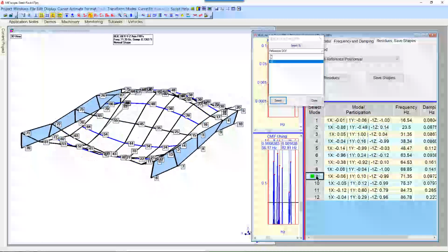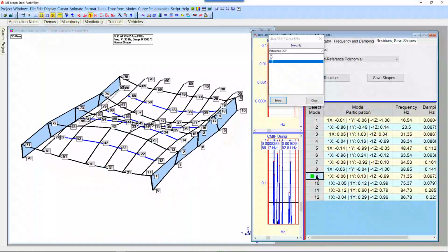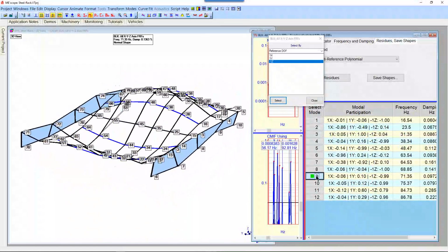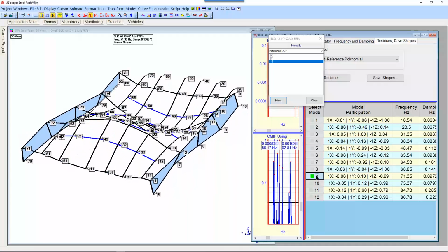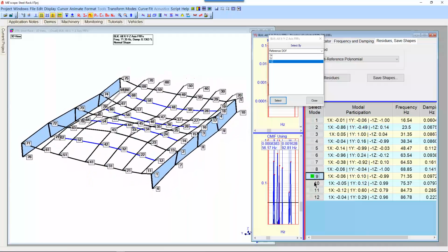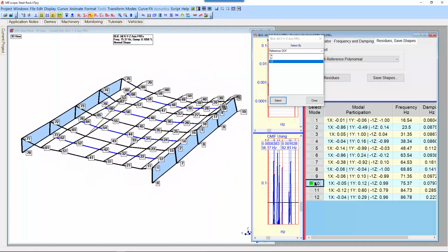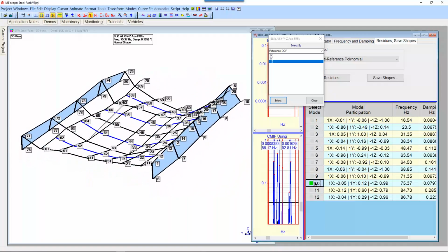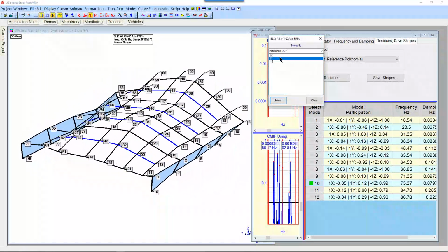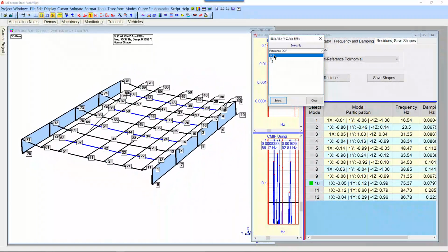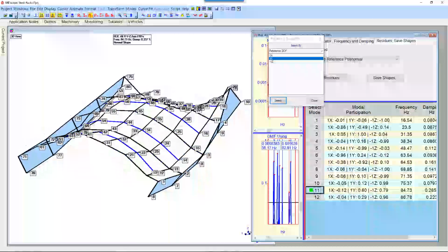Number 9, this again is a Z mode. Boy, we don't have a name for that. We certainly have its frequency. And so we can always identify the modes by their frequency. But this is, maybe you call it an oil canning of this grate, kind of an oil can mode. Here's a, what is this mode? This is another Z mode. A little bit strange as we get up into the higher frequencies. Maybe we call that second bending. The curve fitter has done what it's done. Now maybe I could tweak the curve fitter a little bit, play around with it a little bit.